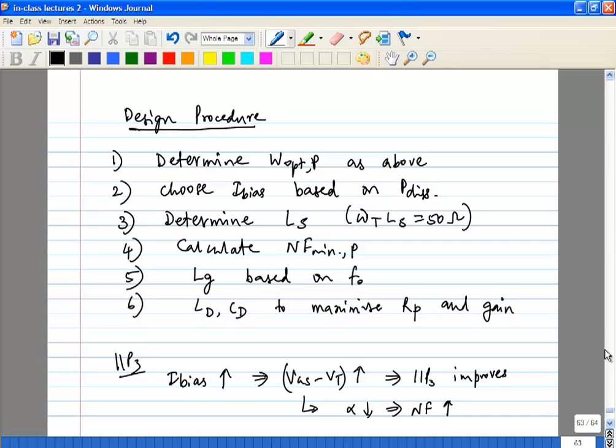But I assumed what he was asking is that because the output swing increases, it could impact linearity, again IIP3, in a second order way, right? So that is what I assumed you're talking about. The swings at the output, you're right, will never go to volts. This is not like a power amplifier. Swings will be very small. The only thing you could see is the swing affecting your linearity, maybe if the swing gets high enough.